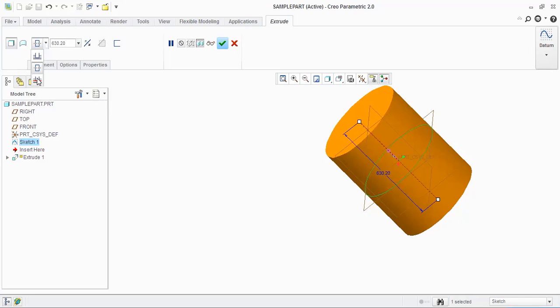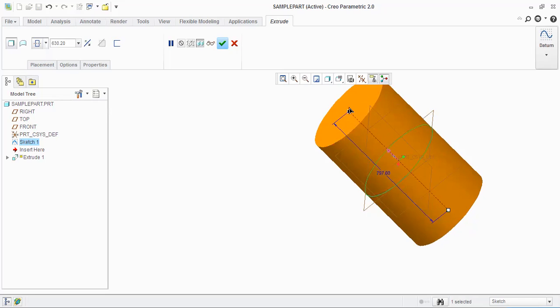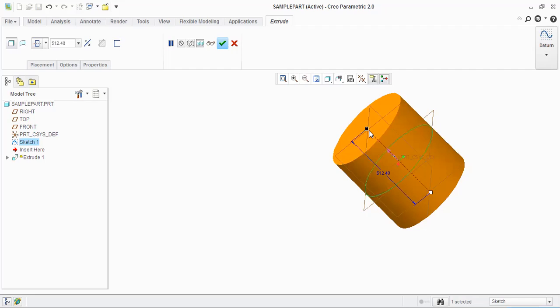And the third one means extrude to selected point, curve, plane or surface. So we can extrude our part up to the next plane. That's why we do not mostly use this third extrusion. We mostly use the second extrusion, extrude on both sides. If you select this, then from that plane at equal dimension, all the extrusion will happen.